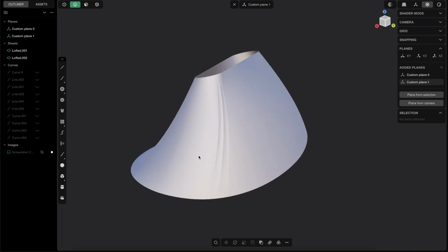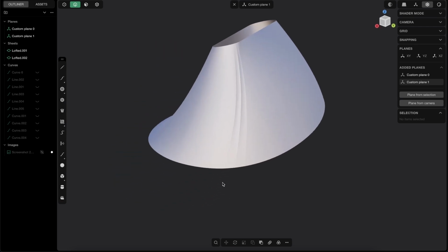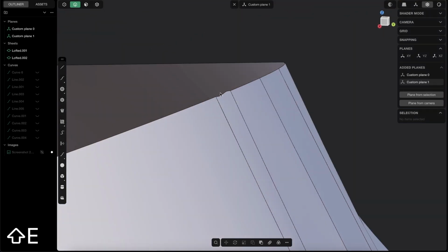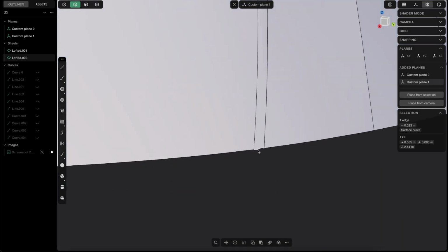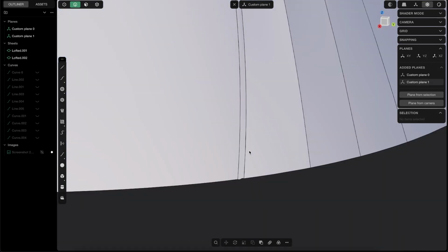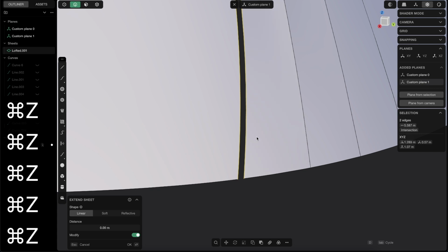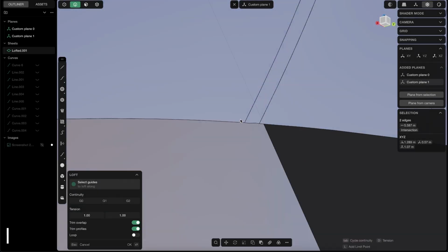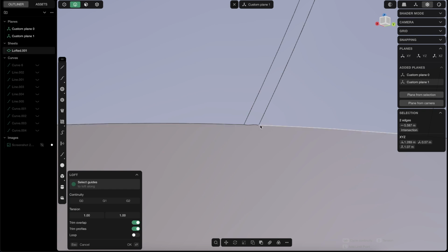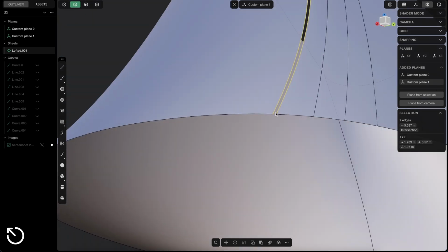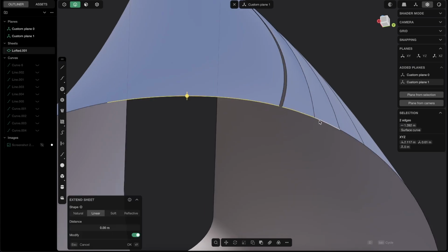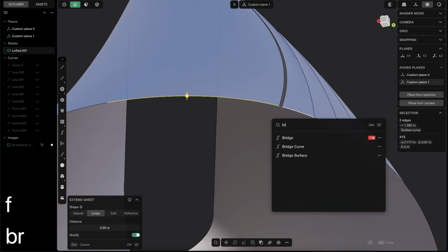And still we have one problem. I intentionally showed you that, because now you see if you zoom in that we have this really weird shape ongoing at the top and at the bottom. That was because, again, go Control Z before you lofted that, because if you just loft it, it does not know exactly where to follow this trimmed edge. So to fix that, you have to just select those 2 edges and search F and bridge.